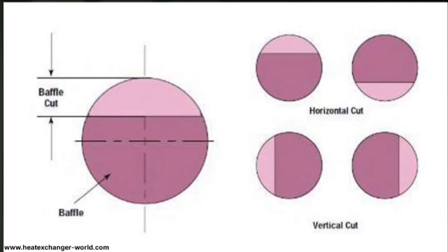Yeah, that's again useless. Baffle means you mean to say segmental cut? No, the open window, any baffle cut. They provided a circular plate, the last baffle. You have not provided the open window. We provided it in revision 0, as per our general awareness so the shell side fluid will flow smoothly. It is not even mentioned in our thermal data sheet, so why would you provide it?